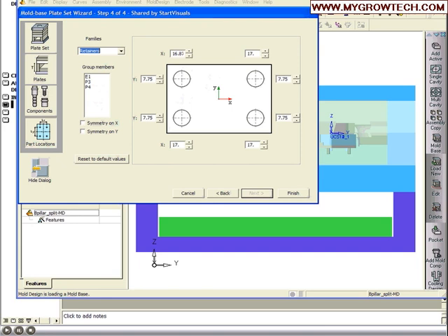And here's an interesting tool. When I look at the different families that are available, I'm actually looking at the location of these standard components. So here are the return pins. The system calls them retainers. We call them return pins. And their location. Perhaps down the road in my design, I've laid out my water, and it's just one, but it's too close to a return pin. Do I need to move the water? I could, or I could, in this case, move that return pin into some non-standard location.